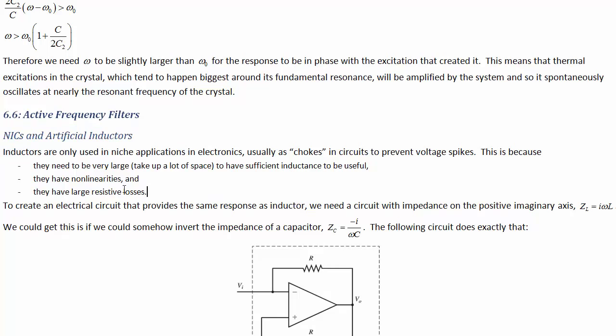Well, if you wanted a big inductance, you've got to take like an iron core and wrap a bunch of coil around it, and that's how you make a really big inductor, which is all well and good if you're dealing with big circuit components. But if you want to build like microcontrollers and have really good filters in there, inductors are kind of out of the question. You can't take this big iron rod with a bunch of coil around it and fit that into a microcontroller. Like for capacitors, you just have to make the plates really close together. You don't actually need a huge amount of area, and you can get the capacitance really big. But for inductors, you can't really cheat like that. It's very difficult to build inductors on the small size scale.